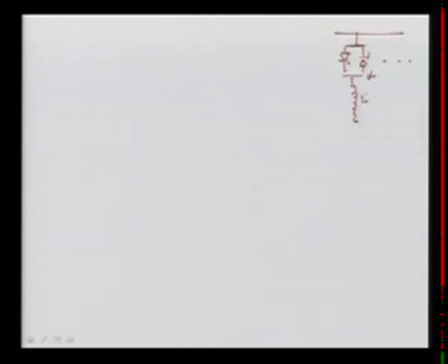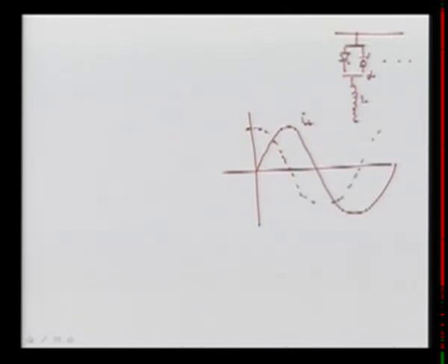So let us take the firing angle as 0, and let us draw the sinusoidal curves here. Here the IL that is flowing, this is your IL current. Now the current will be lagging and the voltage will be leading, so I can draw the 90 degrees here. So I can draw the voltage curve here, again the magnitude will be different, of course, and this is your voltage with the dotted line, that is V.